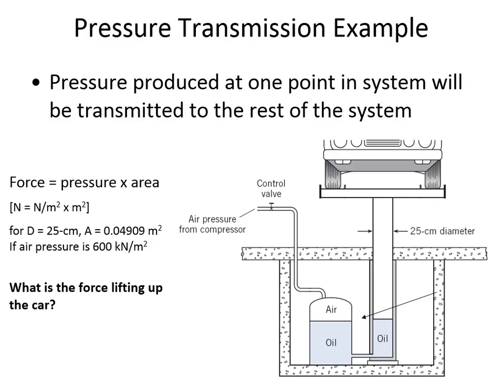But the way that we cause it to rise is that, remember, the pressure is decreasing as we go through the oil. And that's really the key to why it rises, is that we have increased the pressure so that the extra amount of pressure we added causes an additional deflection of this lift, and so the incremental increase in height is just, if you remember, pressure is delta H times gamma. We can find the delta H by being the change in pressure divided by the unit weight of the fluid.